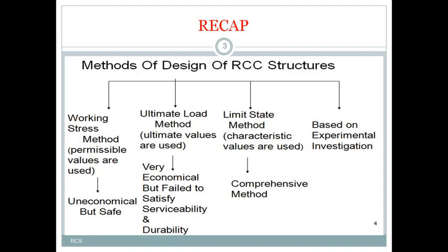Now we will recapitulate what we discussed in our last class. In the last class we discussed methods of design of RC structures. Generally there are three methods: working stress method, ultimate load method and limit state method. And we discussed elaborately the working stress method. This method is based on permissible values of stresses, and here we calculate the working stress. Based on the working stress we design the elements, but the designs made using this working stress method are, we finally conclude, uneconomical but safe.